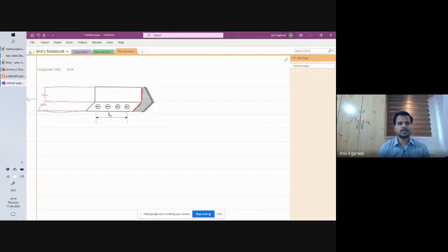And then you are applying some tension force on this angle. That tension force should be acting near the centroid. That may not always be true, but we are assuming that to be true here. Now what is happening is that away from this joint, somehow the stresses are almost uniform, and if they are not uniform, the angle will bend in a way so that they become almost uniform.